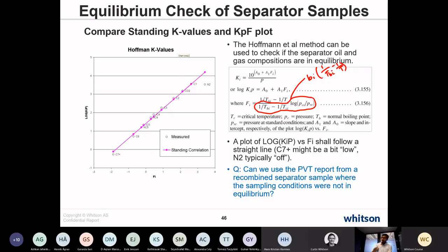Okay, so I guess because we went through the differentiation between the reservoir representative and in situ representative samples, right? We know that any sample that you are collecting from the reservoir at any point in time is considered a reservoir representative sample. And any PVT data measured on any reservoir representative sample should and always be used for EOS model development.